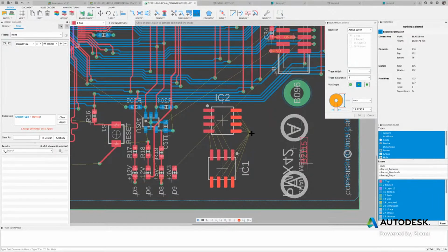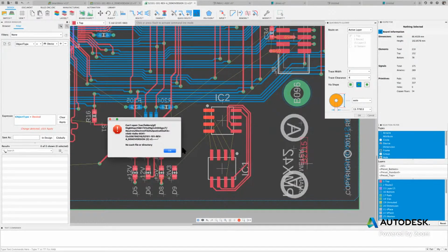And now I'm going to try to influence the path the traces are going to be following. I'll just select here. Now to invoke it, I've given it a predetermined path. Now remember, it's not going to violate DRC, so it's going to do its best. And when I press enter, as you see, it actually does a route. I'll do it again with these on this side.